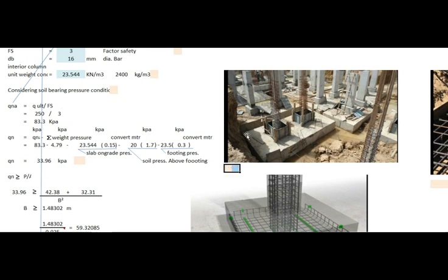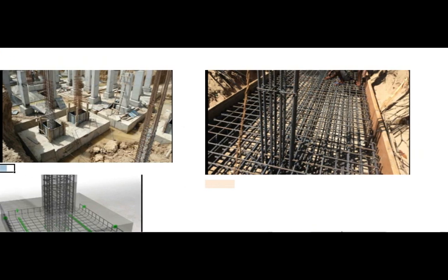This is a sample of a footing that has length, width, thickness and reinforcing bars, but our example is a square footing where the width and length are equal. This is the actual layout of footing reinforcement, top and bottom bars as shown, and column rebars. See the other videos. Prior to pouring of concrete, formworks at the side of the footing are required.